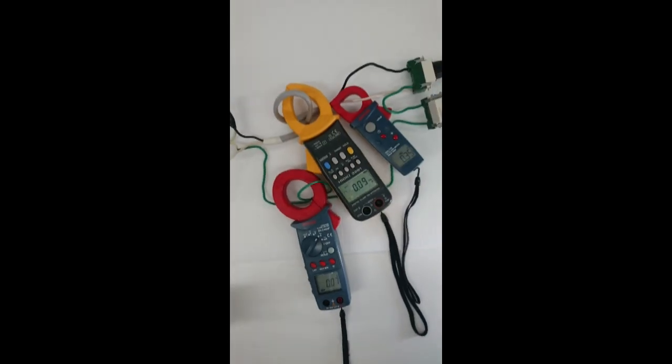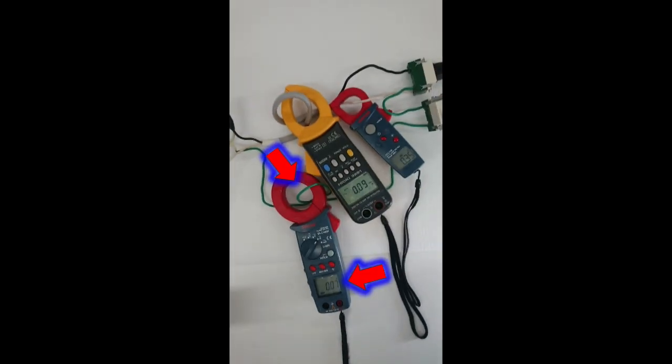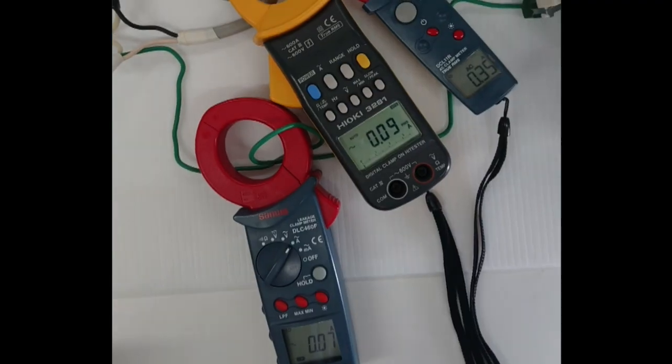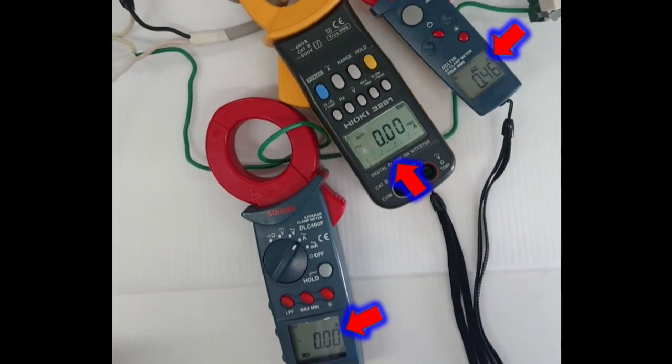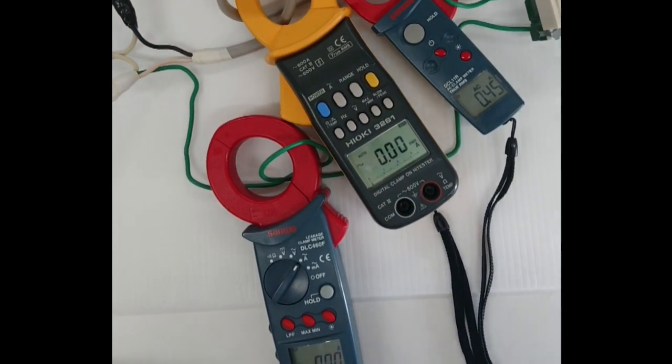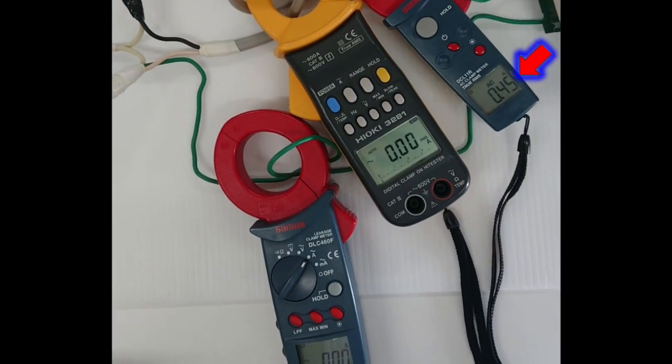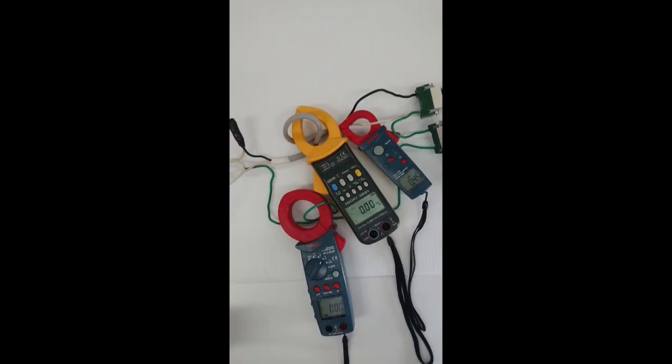When the measured value of clamp 3 exceeds the set value of the earth leakage fire alarm, an alarm will sound to notify you of an abnormality. Turn the ground leakage circuit switch back off. You can see that the measured values of clamps 2 and 3 have become 0, and the measured value of clamp 1 has returned to its original value. The slight difference in the numbers is due to instrument error. This concludes the explanation using actual photos and videos.